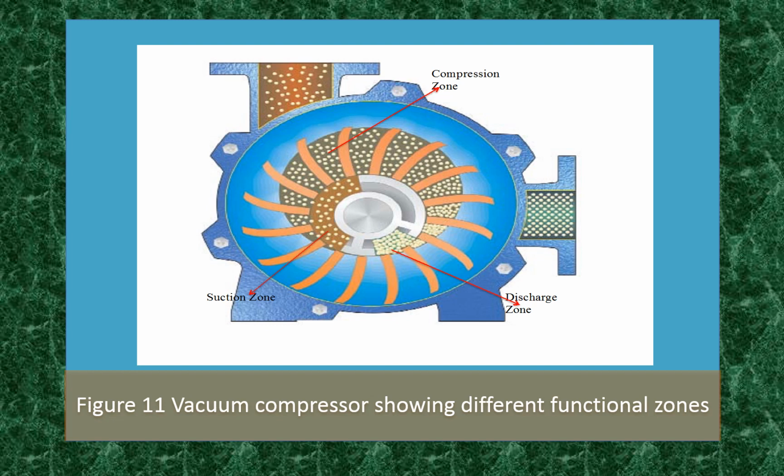Another important type of rotary pump used in the industries, particularly refineries, petrochemical and process plants, is the liquid ring pump. One of the most widely used methods for pulling vacuum is by use of a liquid ring vacuum pump. Liquid ring pumps are pumps in which a liquid ring is formed from the surface liquid, which serves to transmit the energy required for compression of gases and vapors.